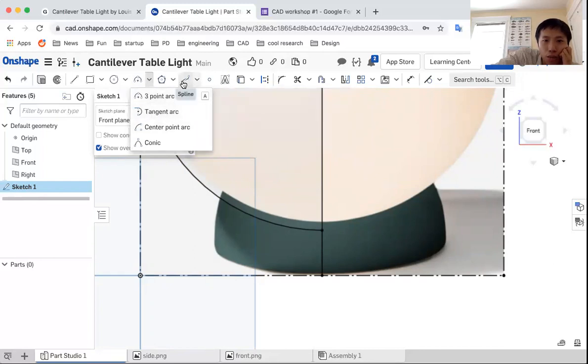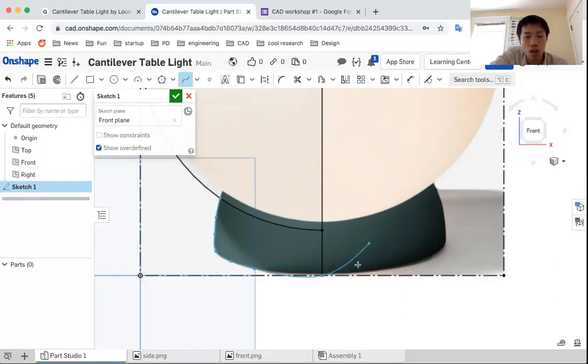So that's when you turn to a function called spline. A spline is basically a really complex curve, and the more points you click, the better the curve is. So watch that. Cool. When you're done, just hit escape, and then you're done.